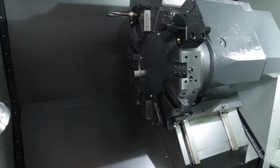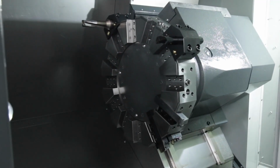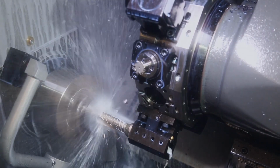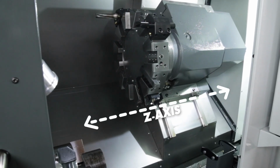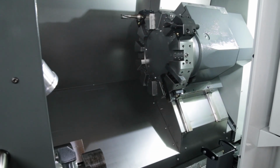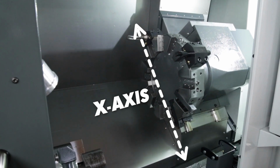a part. As we saw in the first chapter, a typical CNC lathe has a turret that moves right to left as well as in and out. The spindle is what spins the workpiece and the turret holds the cutting tools. The two directions of movement are called axes, and they move like this. The Z-axis moves left to right, and the X-axis moves in and out, or you could think of this as up and down.